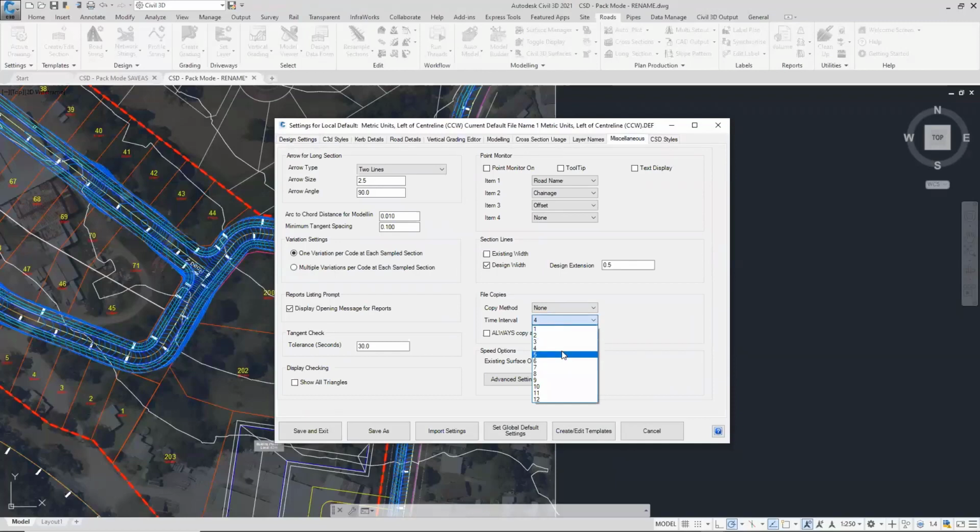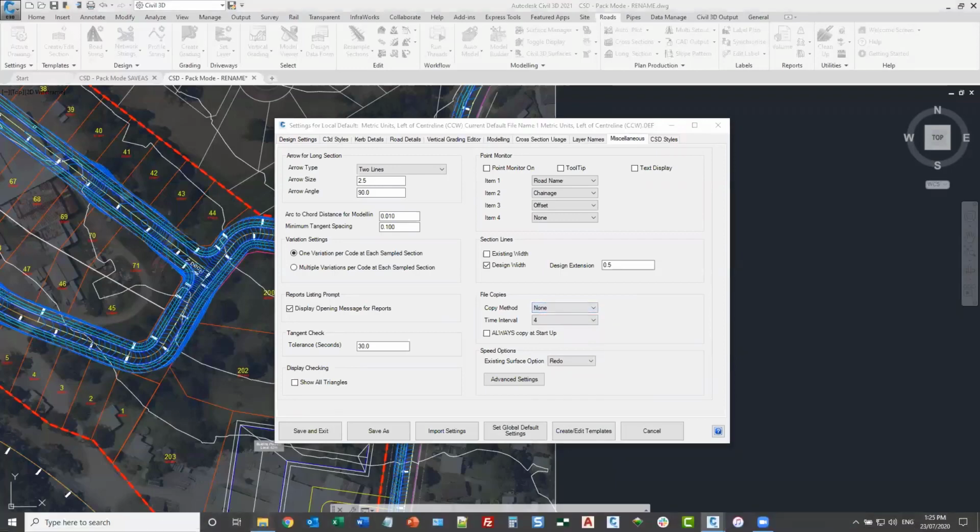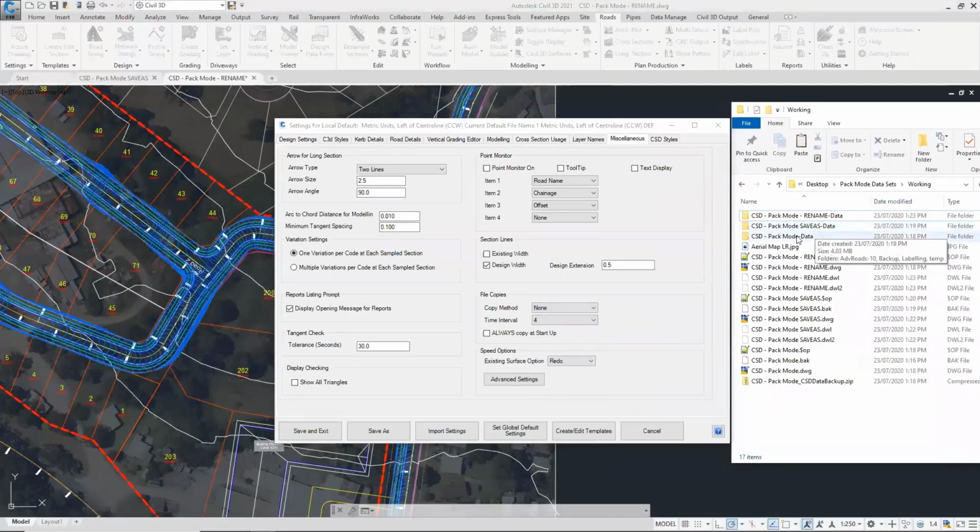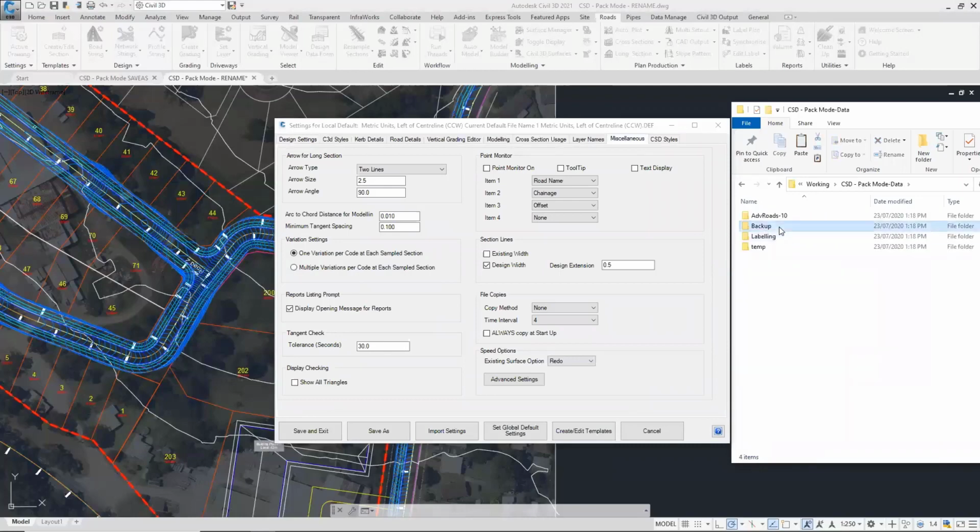This time is not hours, weeks, days, years. This is how often you open up that particular project. So on the 4th time of opening, a copy of my data folder will be created in a file type of my choosing and placed into, for those of you that may have seen it and wondered, this folder here called backup, and it's called SEQ, and then sequentially we add 1, 2, 3, 4, 5. Recommended with this process that you don't have that turned on.